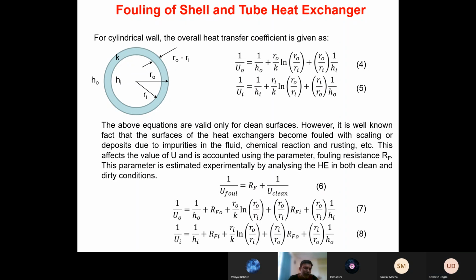Yes, sir. Now, these two equations are valid only if your heat exchanger is clean. But in regular operation, your heat exchanger is not at all clean. Very often, a lot of material gets deposited during the process operation, isn't it? And because of that, fouling and dirt deposition take place on the surface of the heat exchanger, inside as well as outside. And this dirt deposited inside and outside of this metal wall is called fouling.